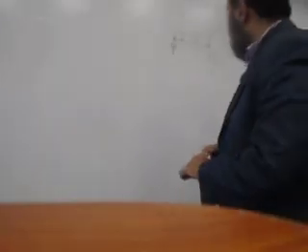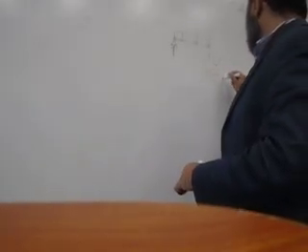So what's shear? Simply speaking, take a whole thing. What's shear? If I hold a piece of paper like this, you have to make it a beam, I'll make it like this. Okay? And it wants to fail. Look. This is one mode of failure. That it's cut like that. So this is the shear force. What's the other mode? That it bends like that. So this is the bending mode. So remember these two. So this is what we call the shear force, the V.